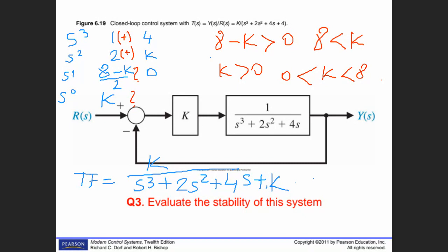So this is your gain. You are capable of controlling the proportionality gain. Assume that if you select 9, then your system becomes unstable. But if you select 0.1, it's all right. You cannot select a negative point. Okay, so K should be higher than 0, a positive number, but less than 8. Okay, your system becomes stable.